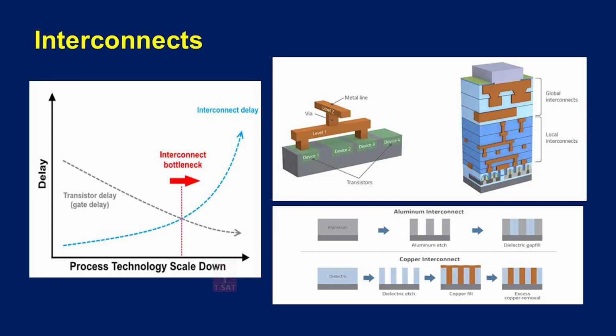In some places we can see the use of gold as an interconnect, but as we all know, gold is precious and it is costly. But the advantage of gold is in applications such as space or automotive, where we are talking about corrosion and extreme conditions. In those very limited cases, we use gold as an interconnect material, but the widely used material is copper.